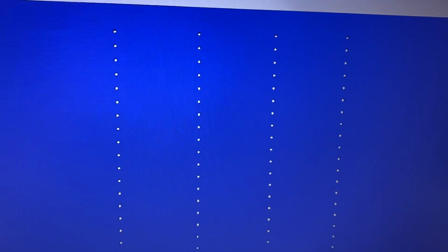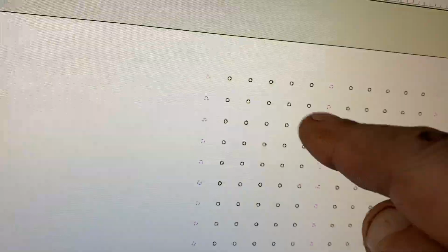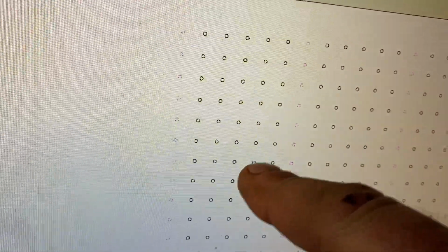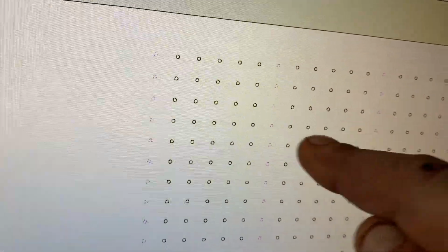So that's the gang drilling section. So that's followed by 5. So you've got one drop in here, followed by 1, 2, 3, 4, 5. So you're actually drilling that block, that block, that block, that block, that block, all in one pass. Okay, and then it'll go across to this one, this block, this block, this block, this block, this block. So we can drill way, way faster using gang drilling.